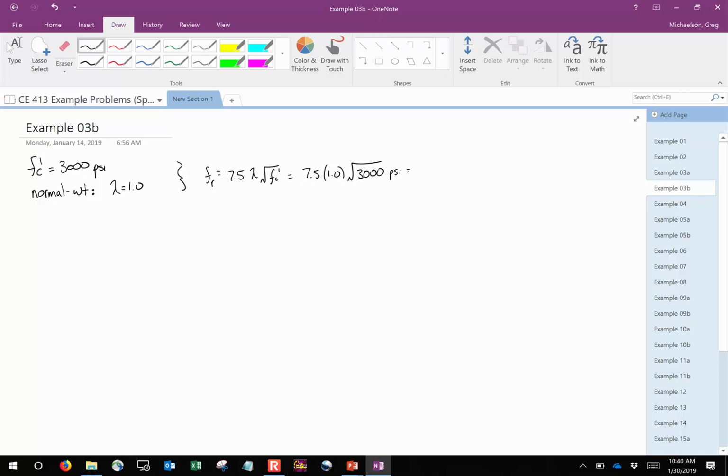So what does this come out to be? 410.79. Okay, so we'll call it 410.8 psi. So I'm just curious, would the beam still have cracked under that 80 foot-kip moment on the last part? No, because what was the tensile stress? What was it, 330 something? 338. So we still hadn't quite experienced cracking. I mean, it can handle probably a little bit more, if I'm guessing something like 100, 110, something like that.